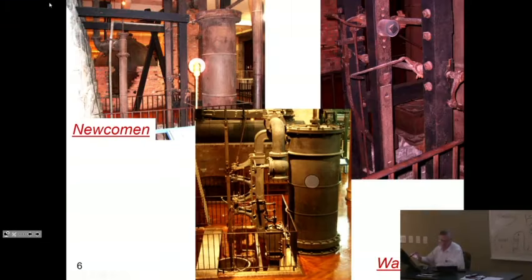And this is James Watt's engine at the same museum. So the piston is still here. The valves, hand-operated valves, are still here. But the cold side condenses into this spot. So here in this trench, this was a canal, this trench is filled with water, and the cold side is condensed from the first cylinder, the main cylinder in which there is a piston, into a condenser cylinder, and thereby gaining a lot of power. Note, of course, that you have more valves, but a single person can handle 2 valves. It can also handle 4 valves, because these engines go very, very slowly.